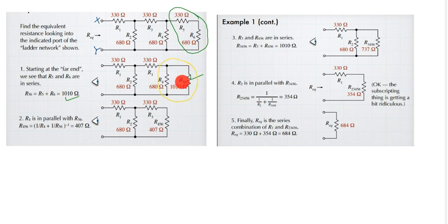The same current cannot flow through them. So R4 is in parallel with R56, which is what I've just explained. So we'll now use the parallel combination approach to resolve this, which will give us R456, that means the resistance resulting from this combination.